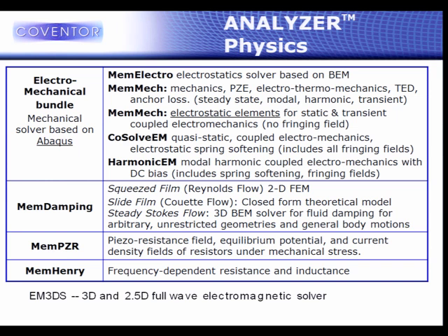The thing you have to watch out for, and people generally aren't aware, is that the elements in ANSYS and ours don't have fringing fields. For devices like comb drives, those are not likely to be very efficient. On the other hand, for devices like this varactor that Sham showed you, the fringing fields probably aren't that important, and you can use this approach.